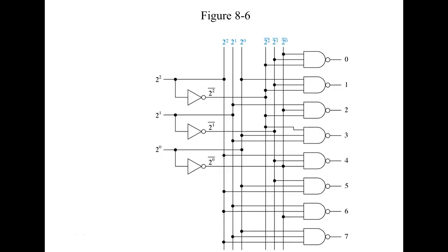Just doing like this. So I just add more NAND gates or whatever, depending on whether it's got a low active output or a high active output. The 7442, the 74138, and the 74154 have what we call a low active output. So it means I come up here and I put a binary number on the input, only one of these outputs is going to go low, depending on what I put on here.